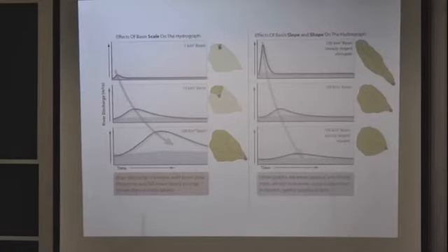The shape of the basin also matters. If there is a steep slope throughout the basin, it will provide a peak in the hydrograph. And if the sizes are the same but the shapes are different, an elongated and steeply sloped basin will provide a different peak compared to a flat one, which will provide a very mild peak flow. So it is less prone to flood compared to the elongated one.